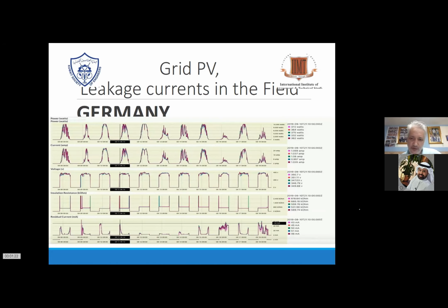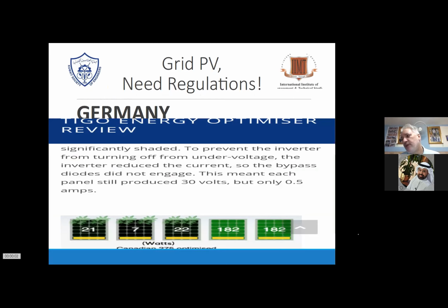Now, when it gets wet, as I said, morning dew or nighttime, you have these problems: the leakage is 10 times higher, and this leakage will switch off the inverters, and you have a lot of phantom ISO faults, which you should not have. The leakage of each individual inverter, in this case, for example, you can see is 43 milliamps in the bottom column, up to 60 milliamps. And each individual inverter manufacturer normally also gives you in the instructions the maximum amount of current.